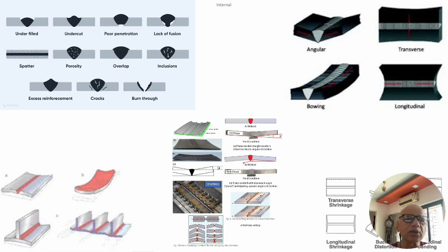But along with the internal defects, these are the external, the third kind of defects, which is the operation successful, patient died. You have a good sound weld meeting all NDT parameters, meeting all the strength requirements, meeting all the visual requirements, but it is having a distortion by which the equipment cannot sustain the design loads and the equipment is going to fail. So we have to really take care of both these kinds of defects, and only then will we be able to make a good equipment. And there are other remedial things which we will be able to take up.